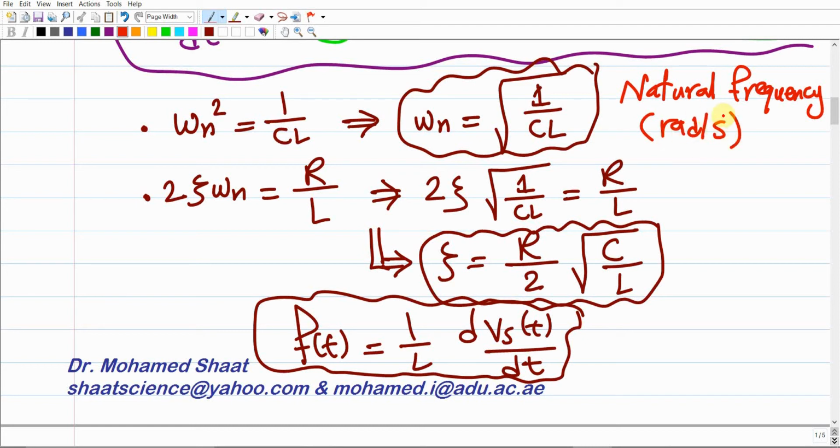Because, as you know, the frequency generally would be in hertz, which is just like cycle per second, or radian per second if we are talking about angular natural frequency. If you remember this from when you studied the waves chapter in physics class. We're going to go over this natural frequency and explain its physical meaning. This one is known as the damping factor, or damping coefficient. All right, so this is the damping factor, and it is dimensionless. Dimensionless means that it shouldn't have any unit.